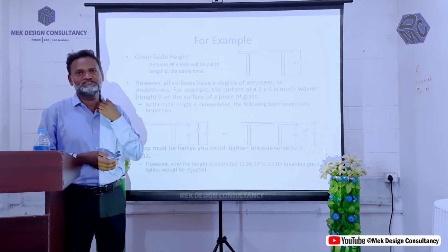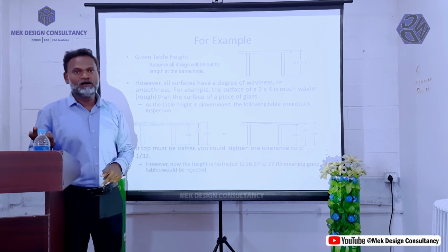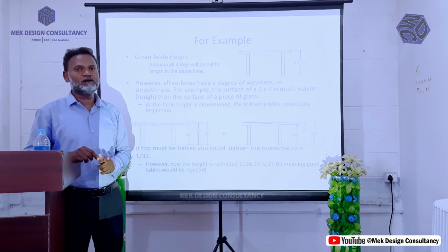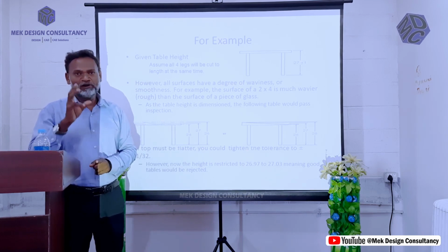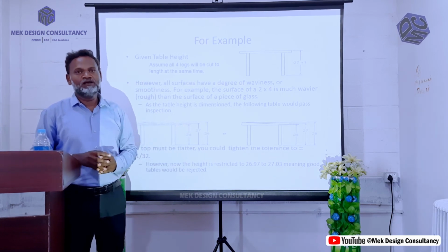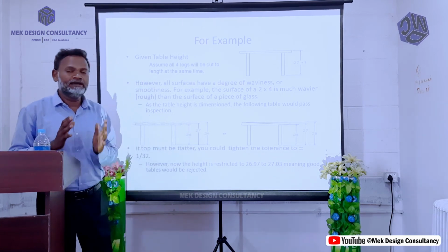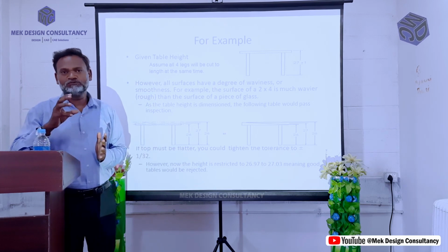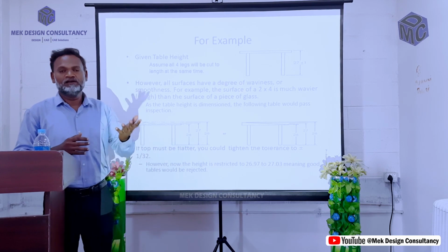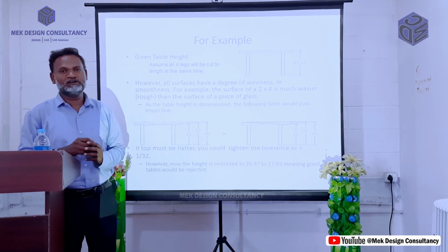They could see the dimensions and the basic parameters, how to manufacture using the basic production process. Once the part is completed, the product should be dispatched to the inspection department. The inspection department is going to use some measuring devices like dial gauges, vernier caliper, height gauge or depth gauge, whatever it is.